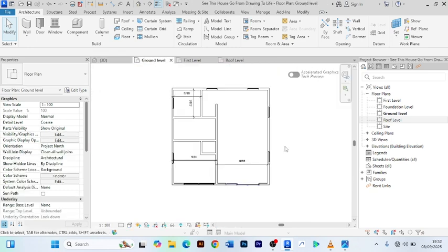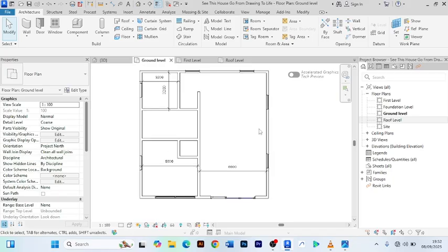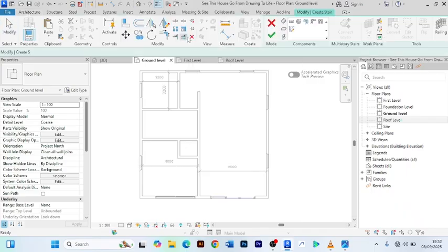When I look at my ground floor, I believe we can still create a staircase here, since this is a storage building. It cannot really make any sense if we do it without a staircase. So we're going to use this space here to create a staircase. So you go to architecture, you come to stair, this stair here, you click on it.